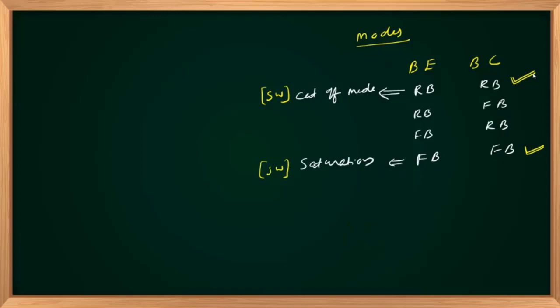And of course, one is cutoff mode. For a switch, cutoff implies zero current. So the transistor current IC equal to 0 or IE equal to 0. Both currents are 0. You can say that IB also equal to 0. All currents are 0 when it is in cutoff mode or open circuit, acting as a switch, position 1 and 2. One corresponding to cutoff, off position, or open circuit.